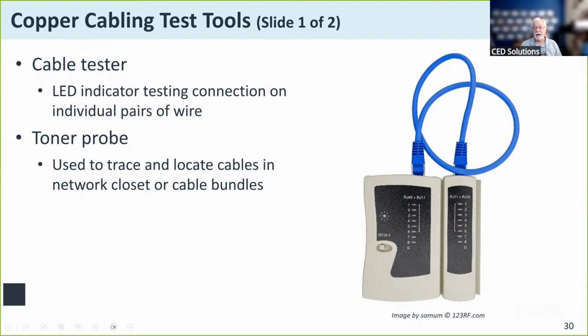Here is a device that allows me to check the wires in a cable, end-to-end cable testing. It tests an 8-wire cable. It'll test each and every wire, tell you if you've got any blockages, if you've got a crimped wire or a broken wire down the line, and most of them will give you, in addition to LED lights that show you the strength of the signaling, audible tones, some of those.